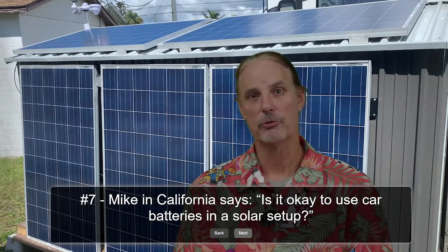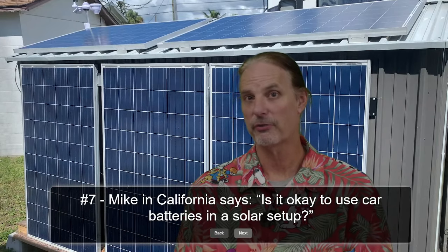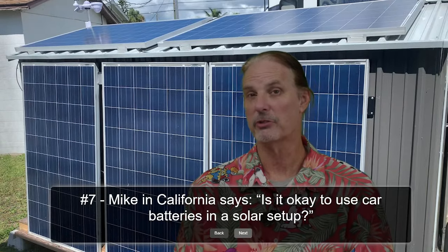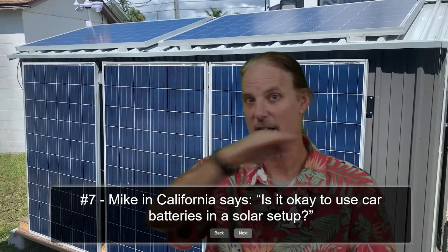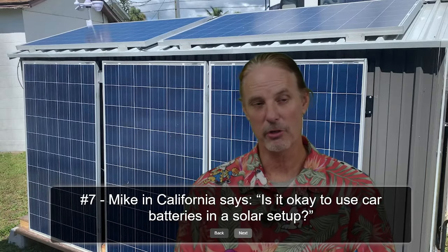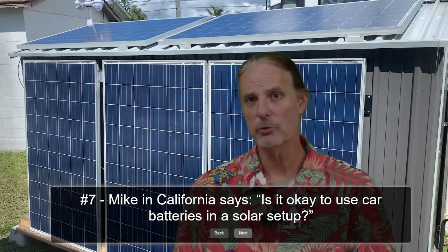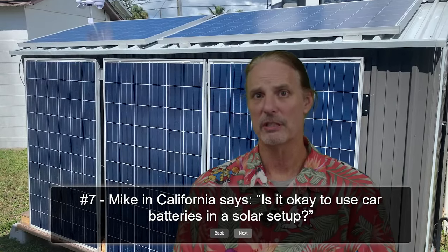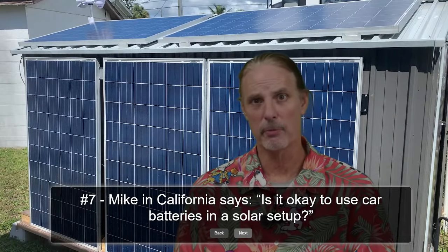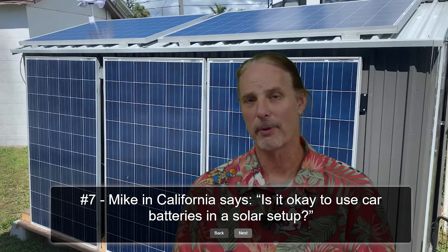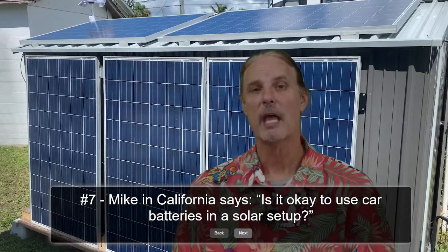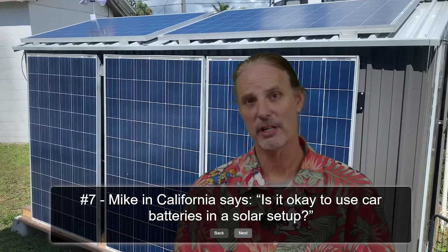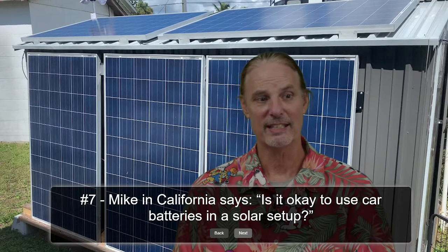Lead acid batteries, they do work. They don't suggest that you bring their state of charge under 50%. They are easier to determine their state of charge based on voltage because they don't have that flat line of voltage scenarios there. But definitely you can use them. They just have a whole variety of other problems that you need to deal with. You need to make sure you keep up with the water. You need to make sure you keep up with maintaining them, and you need to be very careful about discharging them too far, because when you discharge a lead acid battery too far, it damages it.